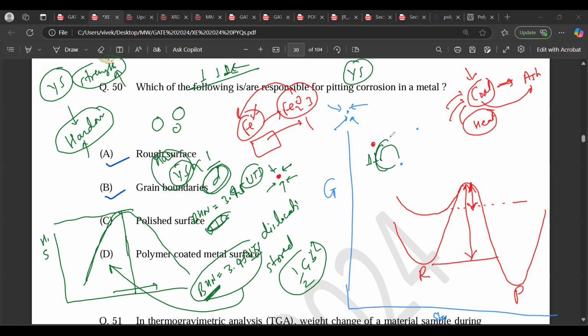The moment you stop this dislocation from moving, like when you create a precipitate here, the dislocation will start to move, then start bowing, and then it may cut through, or it may just bow and make a loop around that precipitate. So you are providing precipitates in the path of dislocation motion, and once this motion is obstructed, your strength shoots up, right?